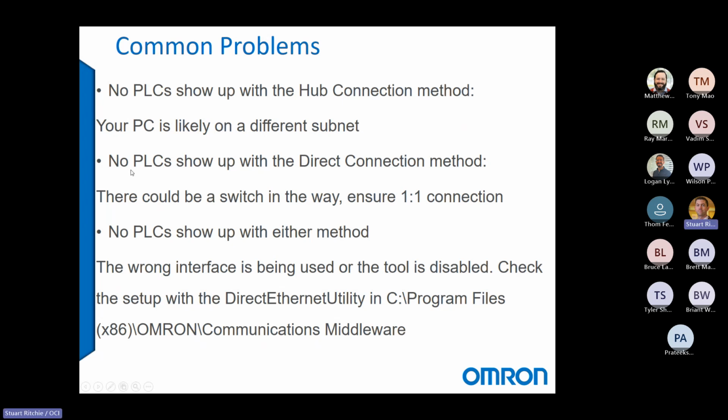Another common problem is no PLCs show up with the direct connection method. And this one, I just need to reiterate, it is a one-to-one connection, so one Ethernet cable from the PLC to the laptop. And worst case scenario, no PLCs show up with either method. And this does happen sometimes.